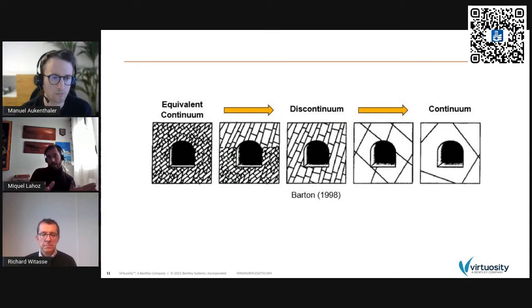What this approach doesn't allow us to model, and for what we will need to be somewhere in the middle, are the localized deformations, so the significant relative displacement that occurs between faces of large discontinuities. And for that, we require perhaps the most complex engineering judgments, because we could have, as in the second picture, a mix of both larger, more significant and smaller discontinuities.